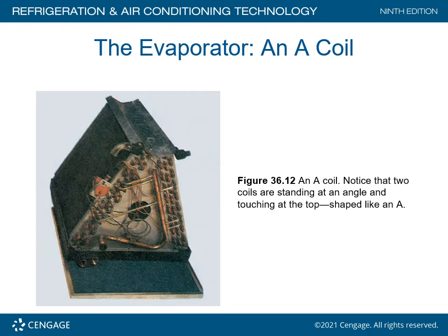It will decrease the heat, resist the heat removal capability of that evaporator coil. It'll reduce the airflow across the coil, and eventually, if you let it go long enough, it'll block the coil so badly with dirt that you're only going to get 30% of airflow through the system, and everybody thinks that the ductwork is bad, when in the actual truth of the matter the underside of this evaporator coil is loaded up with dirt. It does happen on a frequent basis, and a lot of people don't know anything about filters.